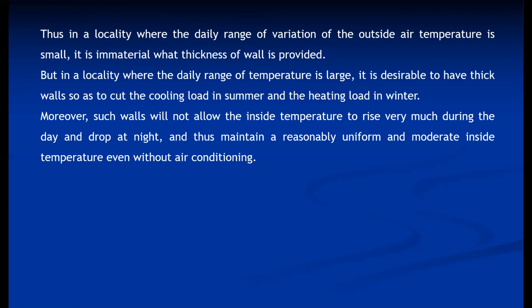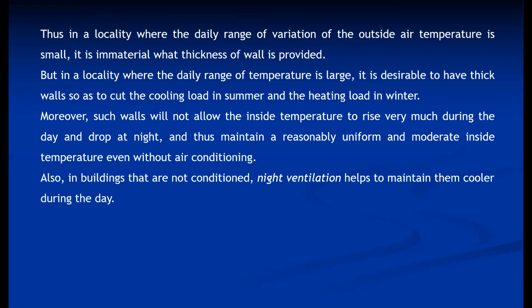Moreover, such walls will not allow the inside temperature to rise very much during the day and drop at night. Thus they maintain a reasonably uniform and moderate inside temperature even without air conditioning. So, as we have discussed, even without air conditioning it maintains a uniform temperature. Also, in buildings that are not conditioned, night ventilation helps to keep them cooler during the day.